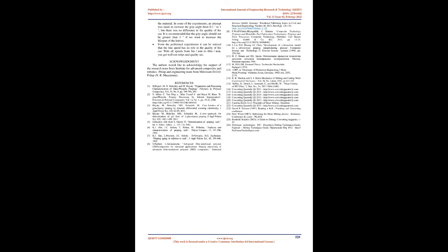For almost all material thicknesses the overlap ranges from 0.6 to 0.8 mm. An overlap of less than 0.4 mm can lead to poor material cut, or the material is not cut at all. The lateral pressure should increase with increasing material thickness and ranges from 0.6 mm to 1.2 mm.